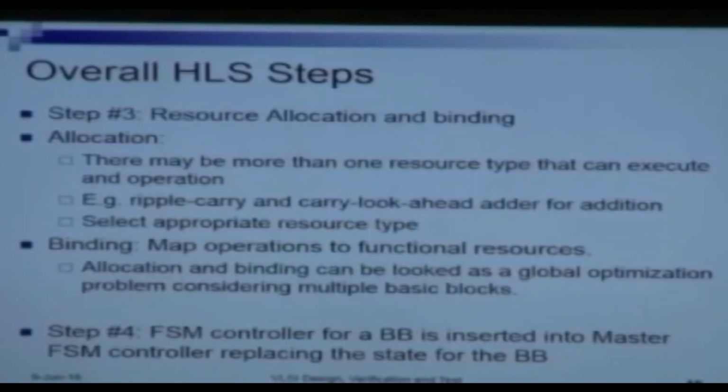The FSM controller for a basic block is inserted into the master FSM controller, replacing the state of the basic block. So in the master FSM controller, I have a single state for the basic block. This single state will be replaced by the controller itself for the basic block, and the timing of the master controller is appropriately adjusted. So with this we come to the end of module 2 of lecture 2.